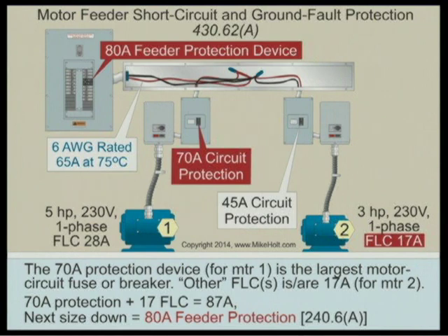Right. It's very important. It's not your calculation of the 250% plus the FLC at 100%. You do your calculation, then you round up to your breaker, then you use your breaker plus your full load current. Right. I knew exactly where you were leading into.